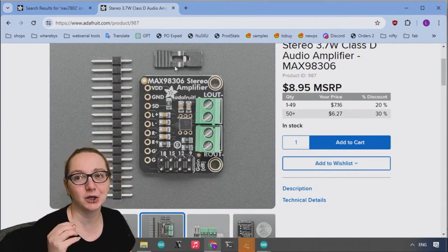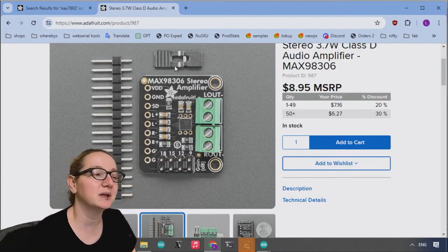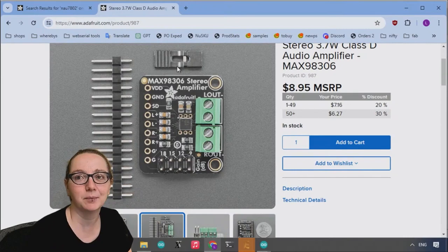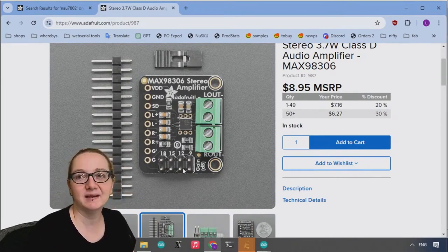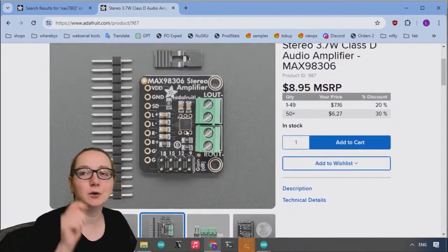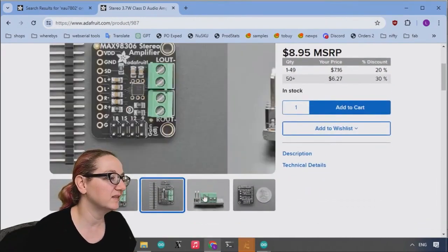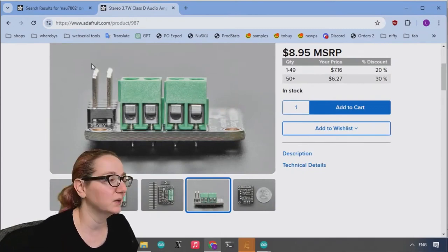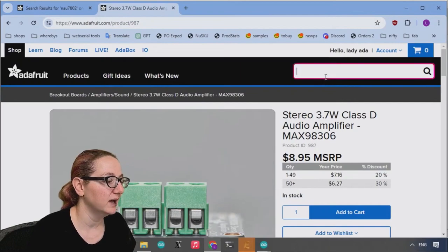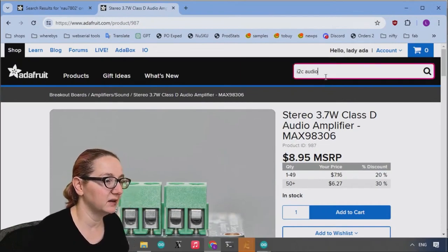But if you're not passing high current, like if you're using it for selection, not for power manipulation, you only have to pass like a milliamp or 10. People lose this, it gets bent. People accidentally maybe put 2, or I don't know, it's confusing. And of course it's kind of tall. If you want something slimmer, a dip switch is the way to go. And we use a dip switch on, I think, an audio amp.